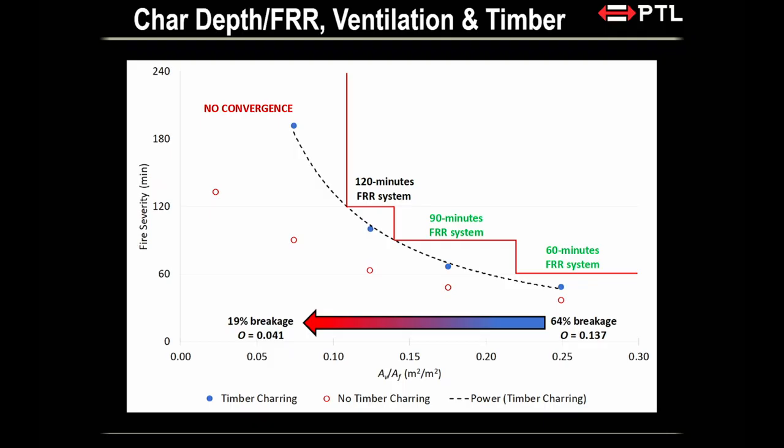It's only one window, so it's very limited in that kind of situation. Now, if you're a little bit wealthy and you can have a penthouse with nice glazing, right? You're somewhere here, 0.2. When you do an open plan office, and what you have is a curtain wall because you're so rich now, then you're actually exceeding 0.25. You're right there, but the rules and requirements don't allow you to break all of that. So there's a cap to it. We're always capped at 0.25, right? So even though you can have a lot of window, it's restricted to 0.25 in typical fire design requirements.